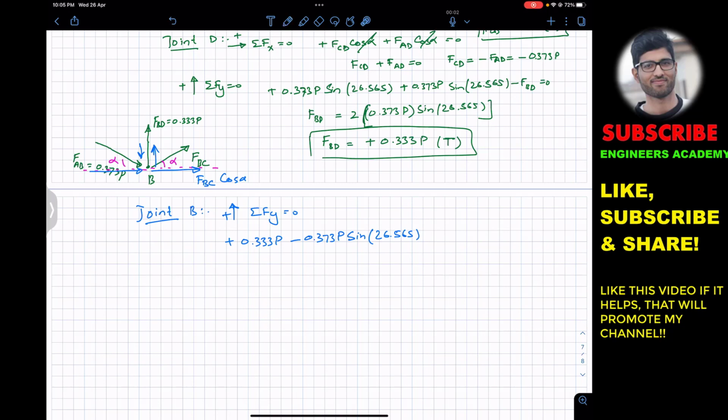And similarly we have the sine component of FBC, which is plus FBC sine of alpha, 26.565, equals 0. So now if I divide this whole equation by sine of 26.565,